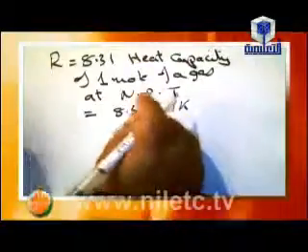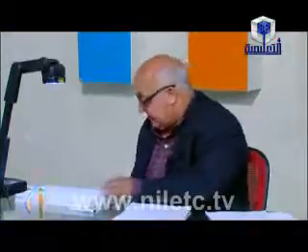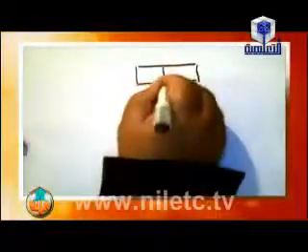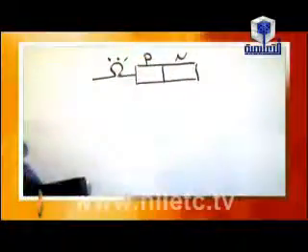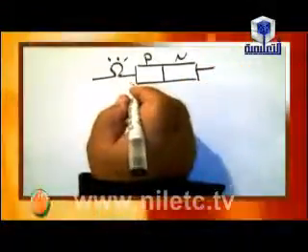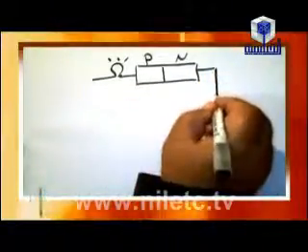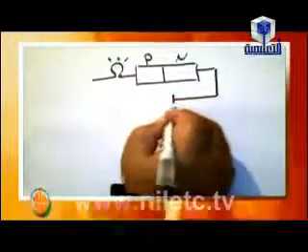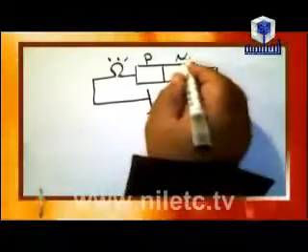And after this, from the figure, we want this lamp to light. We have a diode. This diode is a PN junction. P type and N type are connected together and connected to the lamp. We want to connect a battery with the diode in order to make the lamp light. So we must connect it in forward connection. Forward connection means that the P type is connected to the positive pole and the N type is connected to the negative pole.